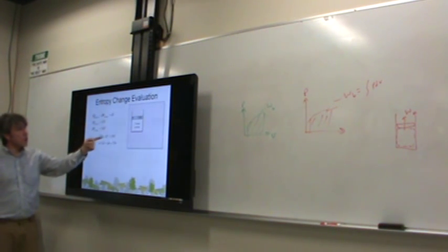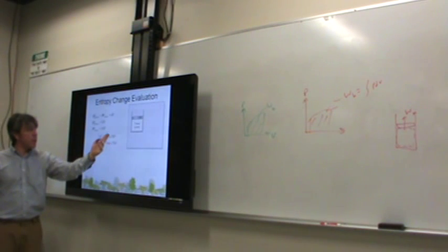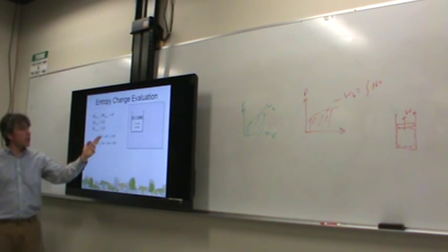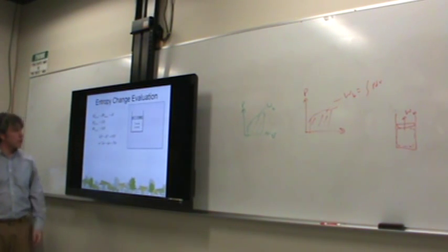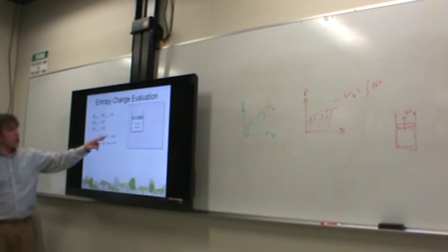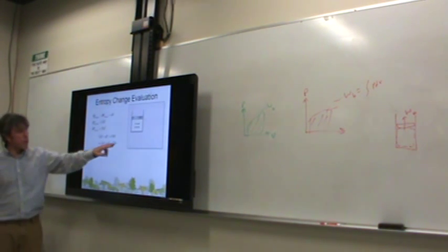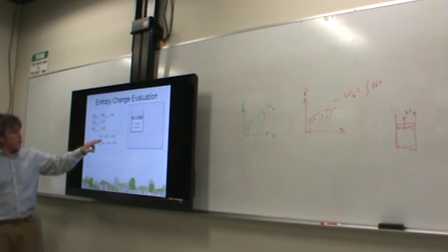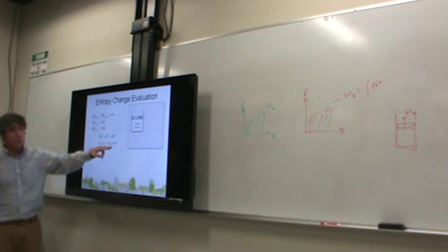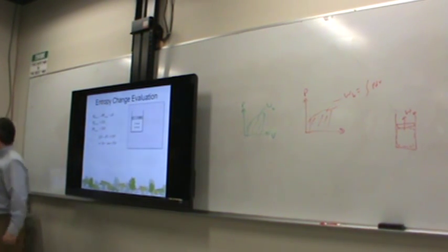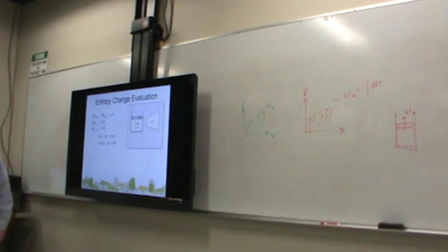Okay. So the equation comes down like this. If we move the work to the other side, it would be PdV, TdS would stay on the left-hand side, and dU is still on the right-hand side. Now we can write this in total form or in per unit mass form. So instead of capital S, capital U and capital V, we have a lowercase version. So this equation would work for both total variables and for specific variables.